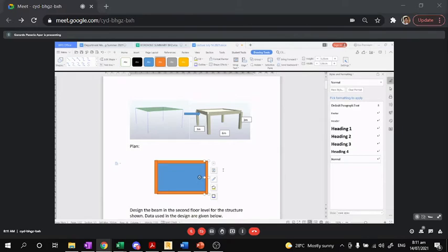So that's the purpose of putting beams on the side, so that the beam will immediately carry the wall system. It's not the slab. So your slab will be free. It will carry only the intended live load and other appliances, if there is, and also the weight system.